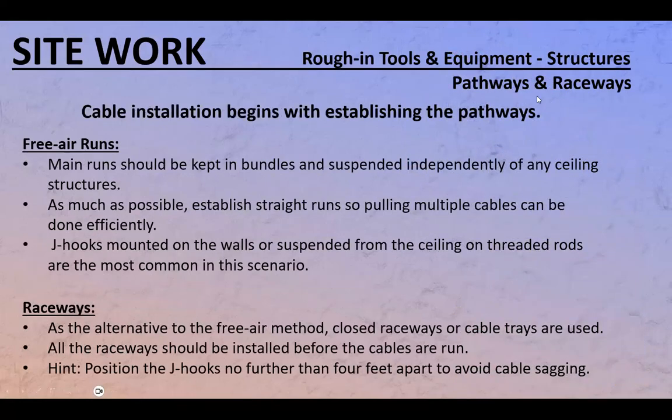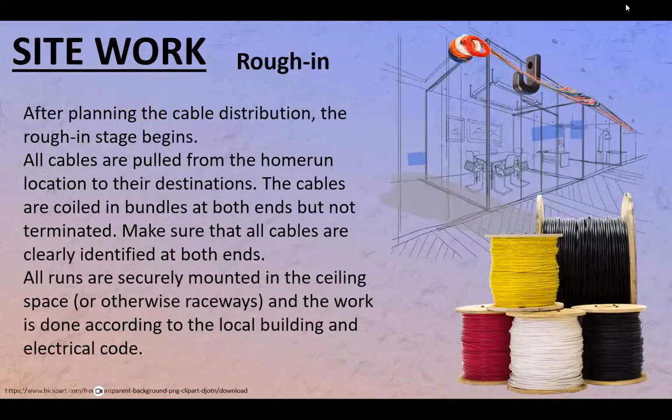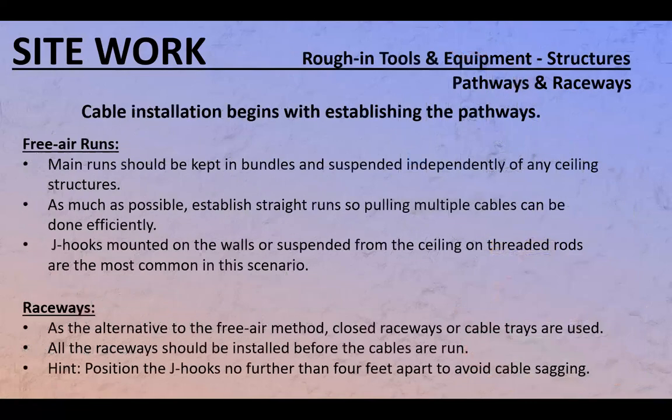Rough-in tools and equipment structures. Cable installation begins with establishing pathways. All right. Free air runs and raceways. Free air runs. That means not in a pipe. Like, for example, this will be a free air run. It's just on the J-hooks, as opposed to cables in a closed pipe.